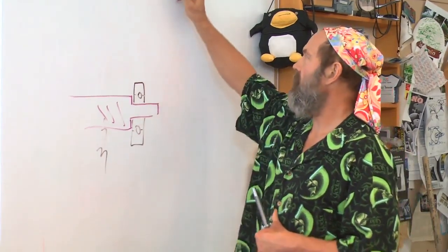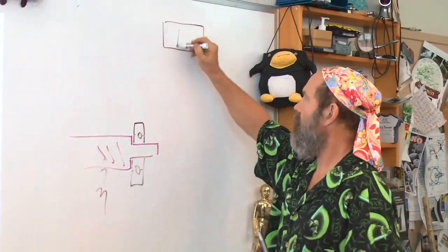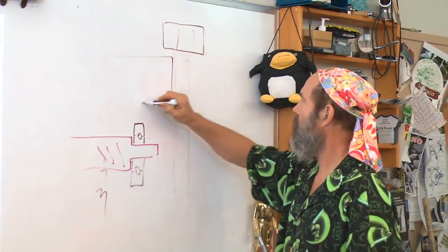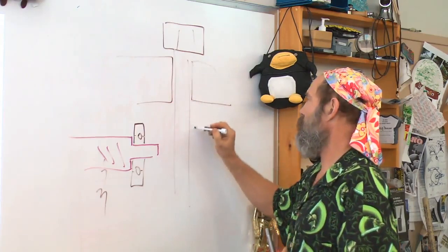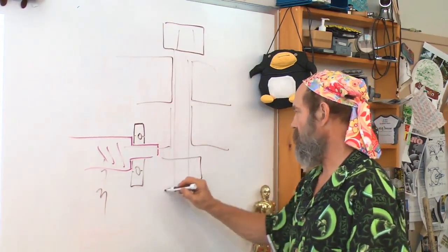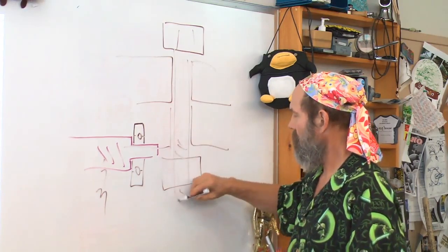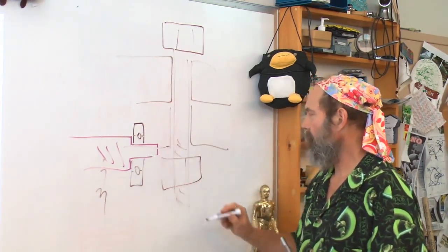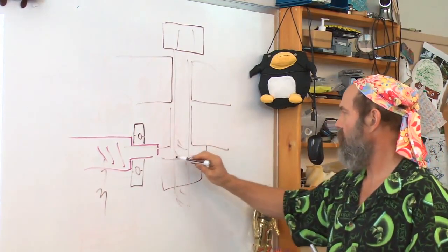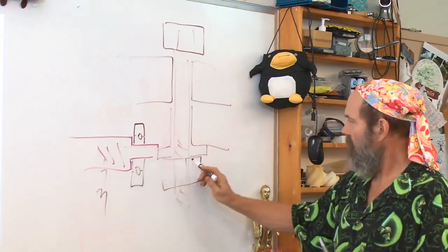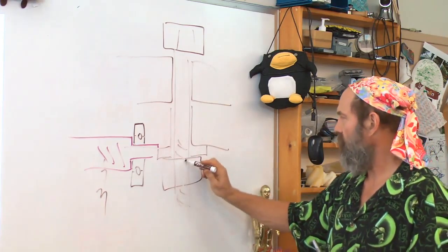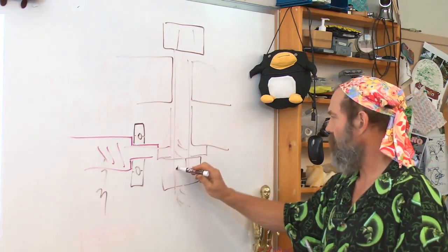If you start thinking about the head of a bolt and you are trying to clamp together two surfaces, because the bolt is just a form of a screw, right? And here's the nut. When this nut contacts, let's say you have a washer in here, the frictional loss between the nut and the screw happens at this small diameter here.